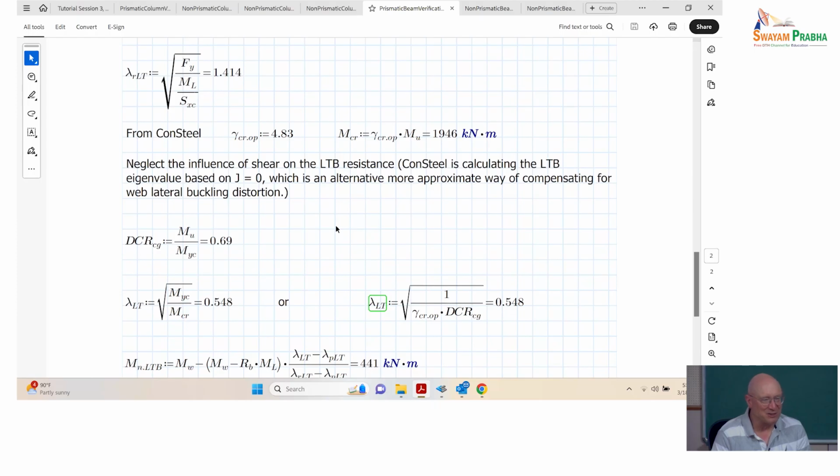It's actually derived from web bend buckling, right? But from the work we've done, we basically said, go ahead and throw it on the elastic buckling, and it kind of makes things better, even though it doesn't have a basis for doing it.